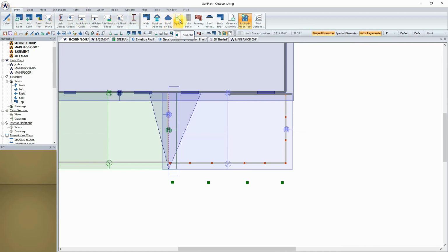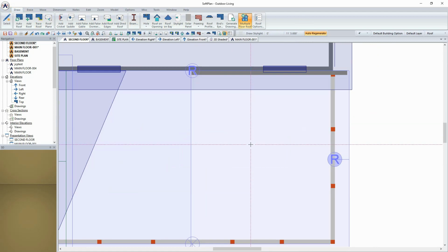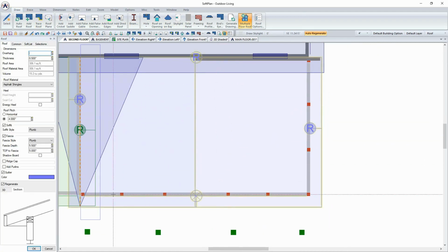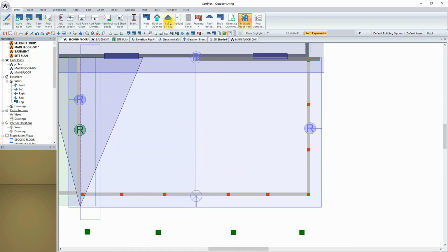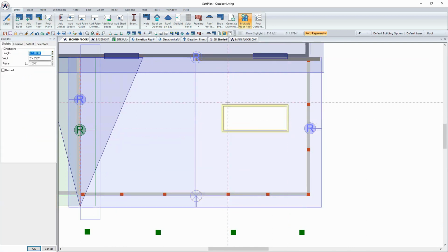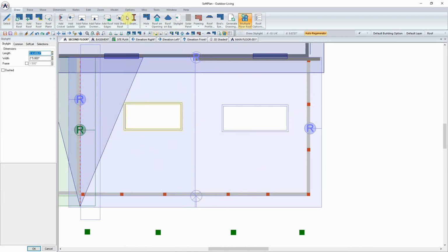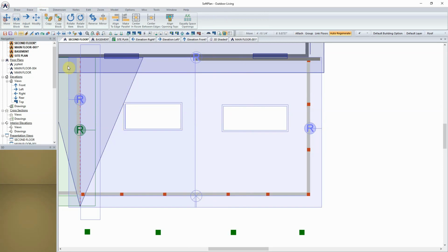As I do that, I can now come in through the draw and skylight option from the ribbon bar, which will now allow me to position my cursor onto the drawing screen, click to begin, and sketch in a similar way as to what I did with the solar panel option, a rectangular box. And the rectangular box will actually cut a hole at this stage through the roof, and if there were a ceiling below in the similar way, so that we can actually have a skylight.